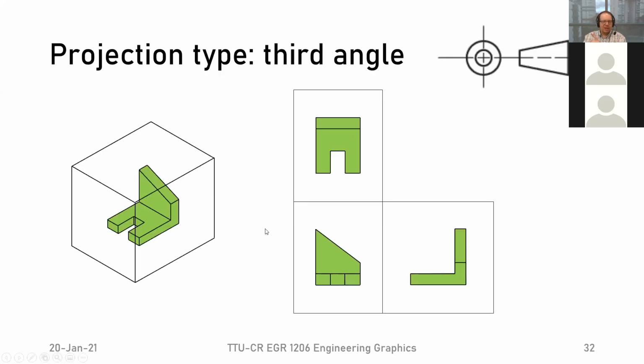All right, I think it's one last thing, or is it? Yes, one last thing. Very good. Now, if you remember back to Monday, we talked very briefly in the title block that we have something that talks about projection. There are two different types of projections that we can get. We can get the third angle projection, which is basically what we have. That's what we talked about: we look from the front, from the right side and from the top, and that gives us the three locations: our front, our right side, and our top.